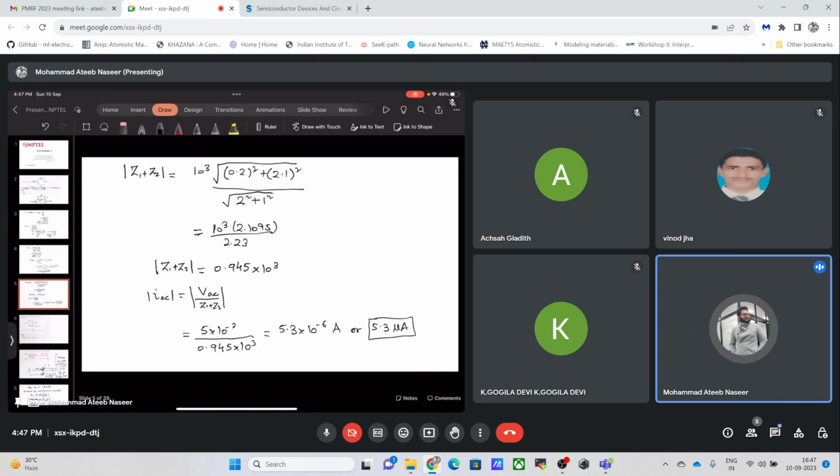And one more thing I would like you to do is that whenever you have an interface problem, go to the band diagram, draw it, make the Fermi level constant, do the charge transfer, whatever carrier transfer is occurring, and see how much insight this simple band diagram gives about the physical system or interface, and you will be able to solve every problem regarding the device physics of the particular material or device that you are studying.